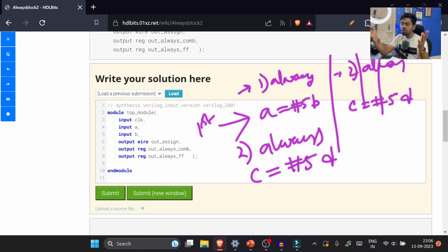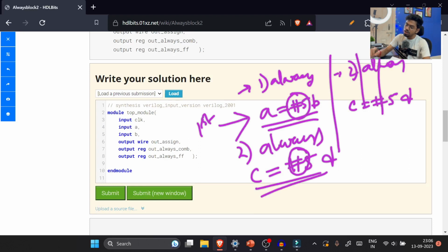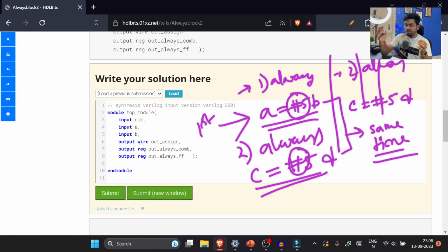But dear, it's a Verilog world. So in the Verilog world, what is happening? Any always block you define, all the always blocks or procedural blocks will start executing at the same time, right? There would be minor differences in your simulator, but we are not going there now. And here we have told our always block that after a delay of 5 units you start this one, and here also a delay of 5 units. So that means both assignments will take place mostly at the same time.